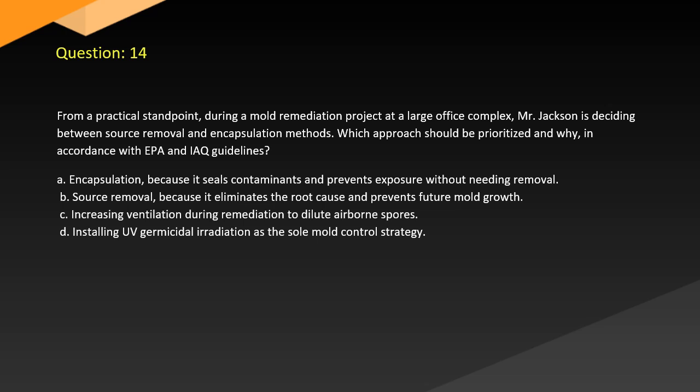Question 14. From a practical standpoint, during a mold remediation project at a large office complex, Mr. Jackson is deciding between source removal and encapsulation methods. Which approach should be prioritized and why, in accordance with EPA and IAQ guidelines? A. Encapsulation, because it seals contaminants and prevents exposure without needing removal. B. Source removal, because it eliminates the root cause and prevents future mold growth. C. Increasing ventilation during remediation to dilute airborne spores. D. Installing UV germicidal irradiation as the sole mold control strategy.